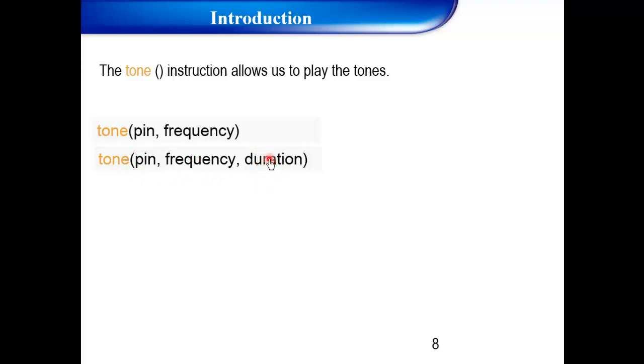Now, if you use tone(pin, frequency), the tone does not stop, and tone(pin, frequency, duration) is for stopping. The duration is written in milliseconds, 100 milliseconds to stop the tone, for example.